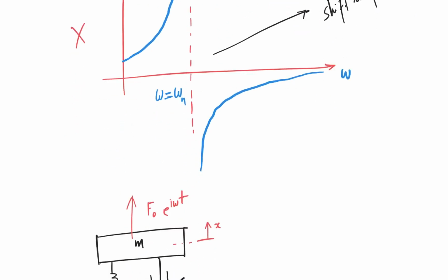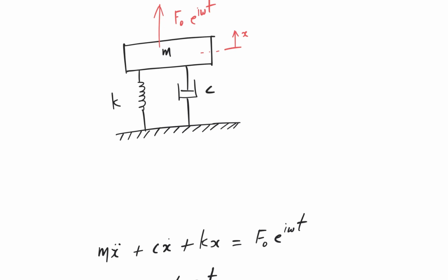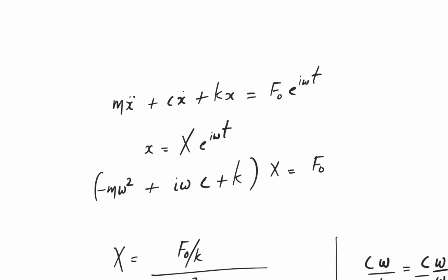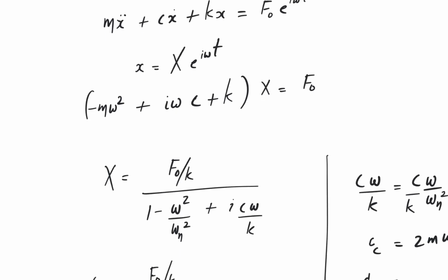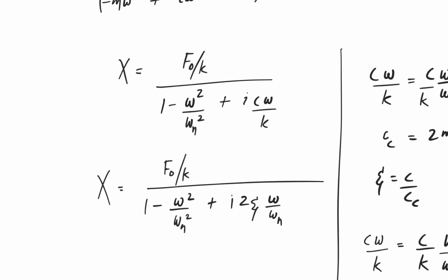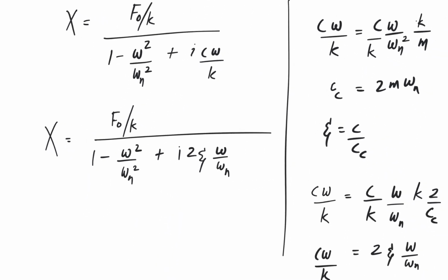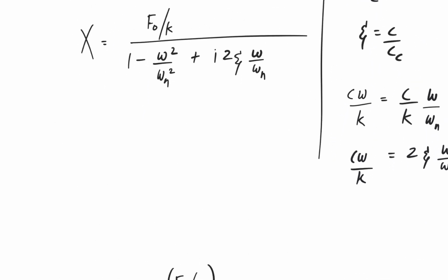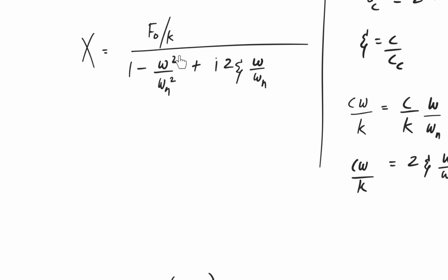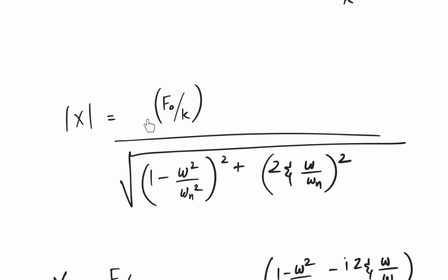Now let us go to a damped single degree of freedom system. Here also things almost remain the same, but the governing equation looks different. But once we extend the same principle we had applied, for a damped system we will get expressions of this kind. I'm not going again into the details of the math. You can pause yourself and understand all these things. But now this is your response. This again is a complex number, but the magnitude of the complex number can be written like this.